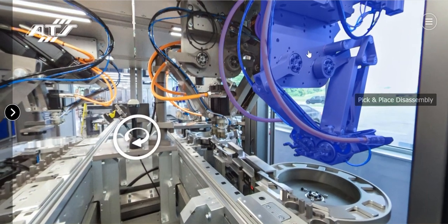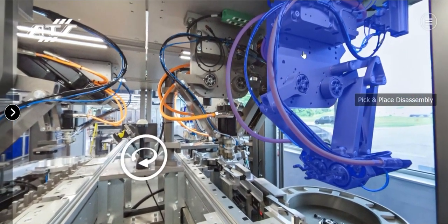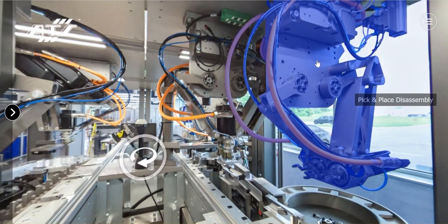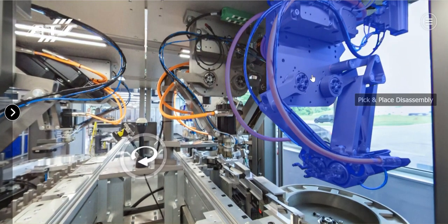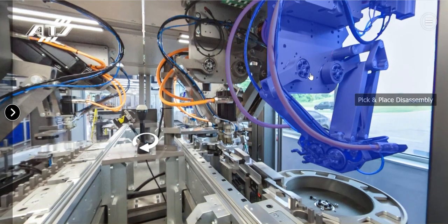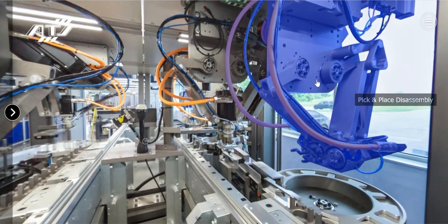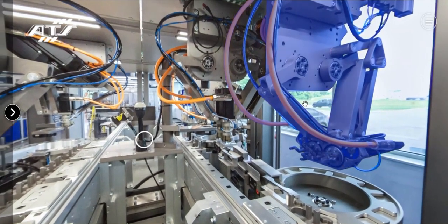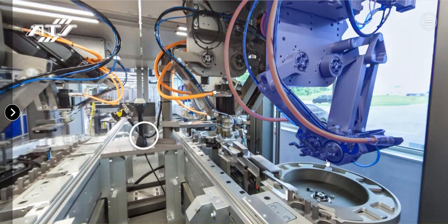So what do we mean by high speeds? Basically, these robots are designed to stroke at up to 200 per minute. We usually don't run them that fast. Usually we limit the stroke rate to 150 cycles per minute, which means that if we're operating 2 up, that gives a nominal output through a station of 300 parts per minute.